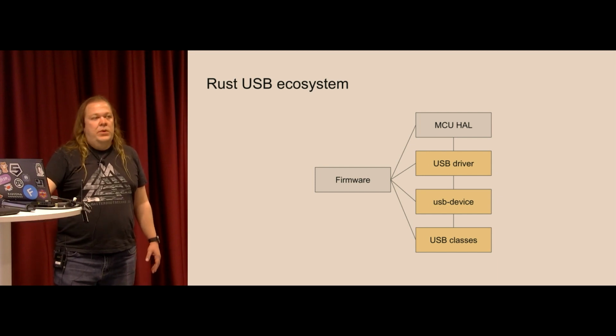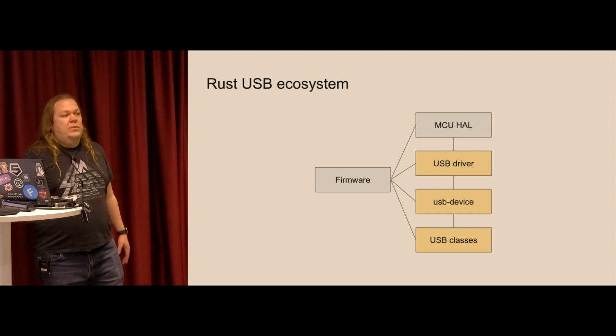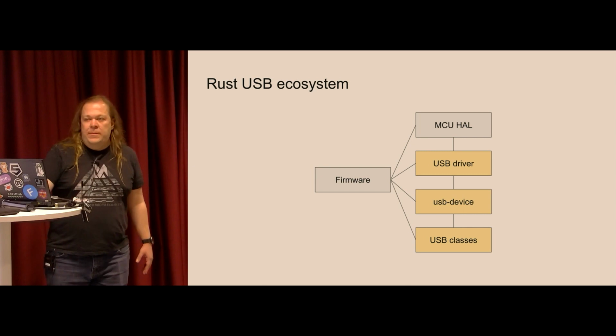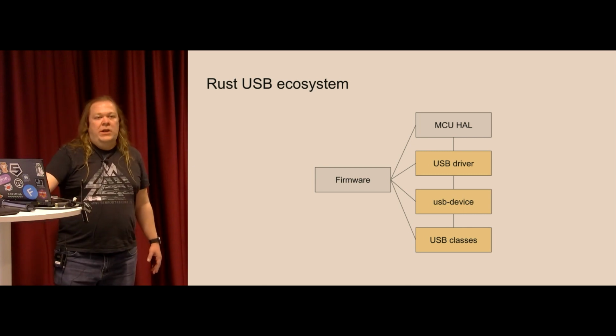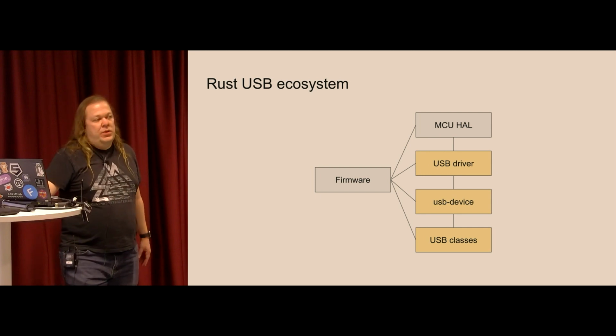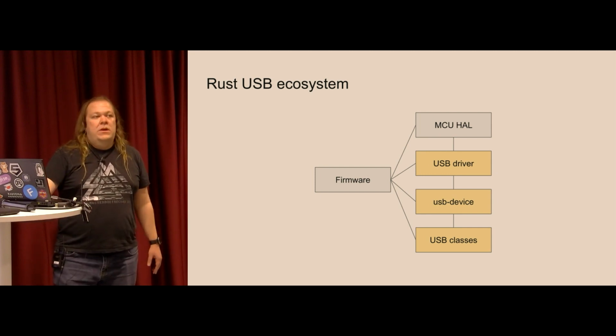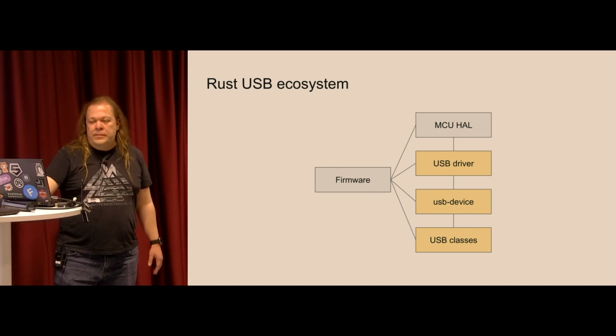So, for example, if you have USB serial, we translate all the requests on endpoints into some stream of bytes. All the requests are packets, and since we implement a serial port, we need to convert packets into bytes and vice versa. So this kind of translation happens in classes.